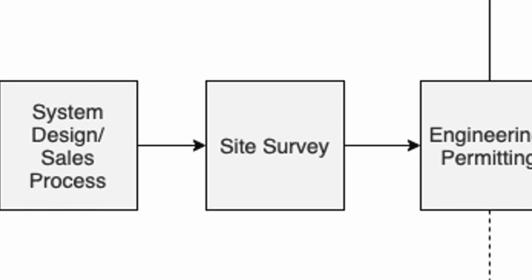After that's been completed, the next immediate step of the process is the site survey. I like to always refer to the site survey as really the most critical phase of the project, because it's during the site survey all of the relevant information is obtained about your property, the condition of the roof, the condition of the shingles, the structural information regarding the rafters or trusses, the spacing, the electrical information. Everything is being done on site to fully audit or evaluate the property to make sure we have the right information when it comes to the engineering phase of the project, which is the next immediate step.